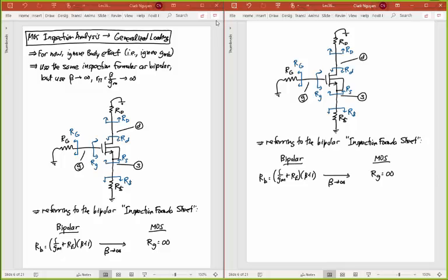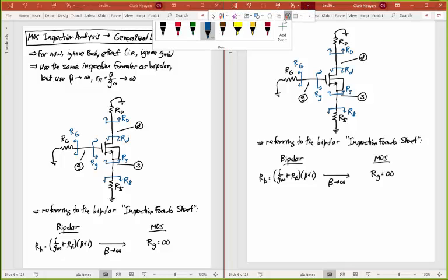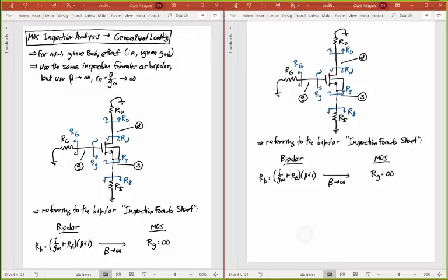And we're going to want gains also from terminal to terminal. So we're doing everything that we did with the bipolar transistors, but we're not doing an inkling of work to do this. I'm not going to solve again by putting the MOS hybrid pi model into a generally loaded circuit and resolve that. I don't need to, because I just said that the two circuits are exactly the same as bipolar, except that R pi or beta goes to infinity.